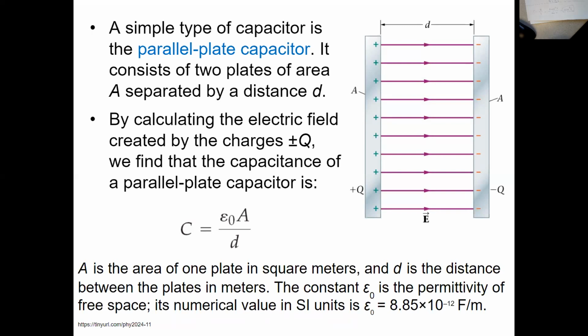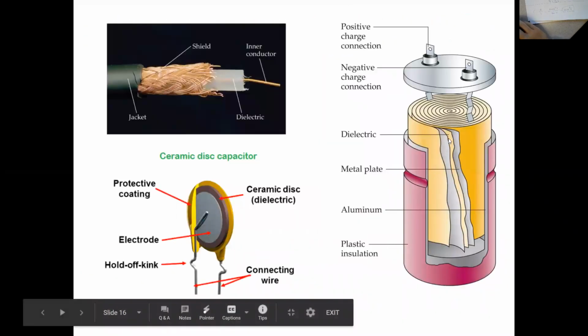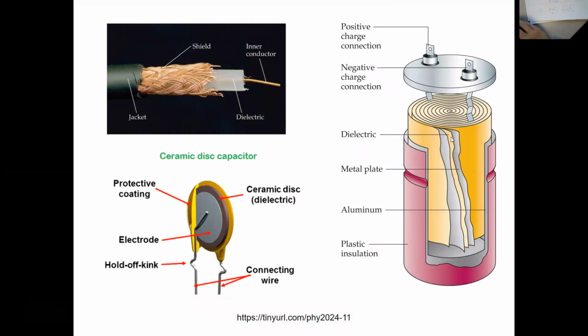So in that sense, you can see the design of the capacitor in a few slides backward. They are pretty much just separated by a very thin insulator. You want to make D very small to reach a larger capacitance, and then you roll the sheets up, so the two metal sheets will have larger area.